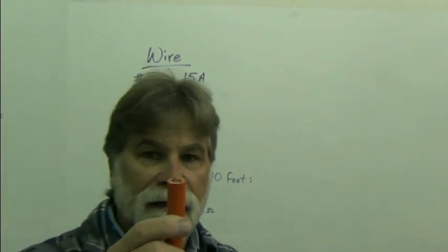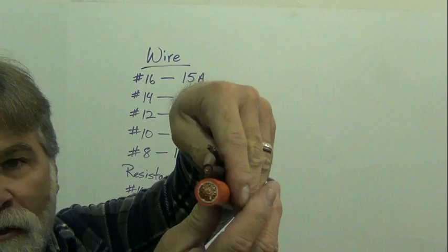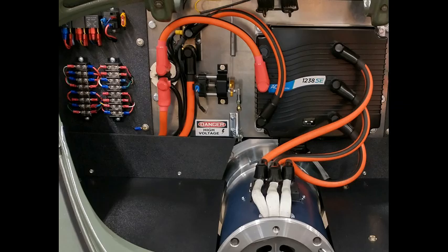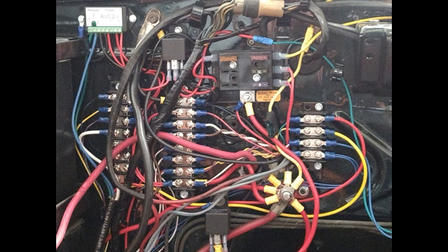This is double aught. Wire and cable are sized by gauge, and I showed you some examples. Remember, the larger the gauge number, the smaller the wire diameter. For instance, 12 gauge wire is larger than 18 gauge wire, and 6 gauge wire is larger than 12 gauge wire, and so on, like I mentioned earlier. The larger the wire, the more current it can carry, and the lower resistance per given foot. For example, a 16 gauge wire is rated at 5 amps for 15 feet. If you needed to carry the same current for a greater distance, you would need a larger gauge wire. For instance, a 10 gauge wire can carry 5 amps for up to 50 feet.